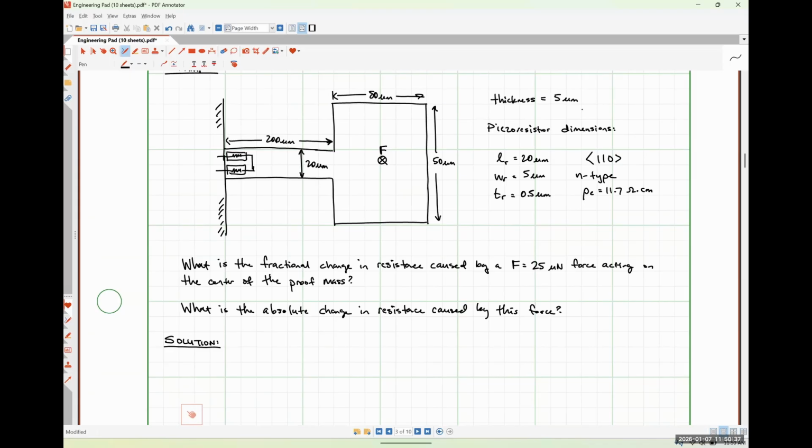And if we had embedded it into the surface of the beam as opposed to depositing it on top of the beam, as we cross that halfway point, our tensile stress starts to become compressive stress as the beam deflects, and so some of that signal is going to get canceled out. So realistically, we want our piezo resistors to be as thin as possible at the point of maximum stress. So that's what I've attempted to illustrate here.